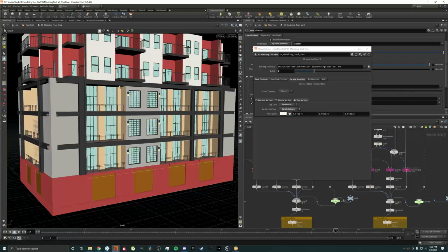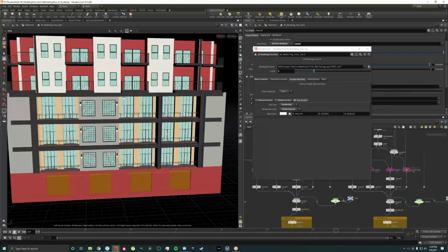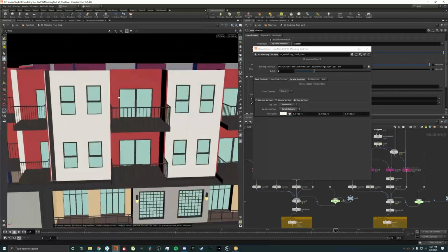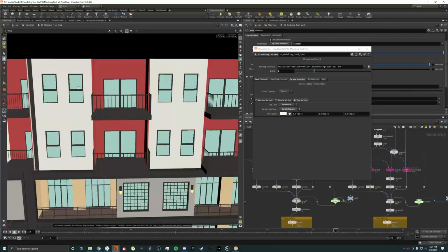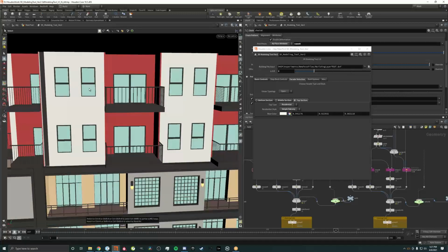So that's great. I really like this because this looks more like the facades that Gerhard's been providing us, which are much more realistic. More like what we see every day, right? Well, that's a big compliment, because these are the facades that Gerhard sent me, I think earlier this week or late last week. All of those reference images, Gerhard. On the top one, I would put the windows. The windows are taller than the doors. Typically, that doesn't happen in a resi building. That happens in offices, but in a resi building, if the window was a little shorter, I wouldn't necessarily make the sill, the bottom piece, lower. Just make the whole window smaller. Push it down a little bit.